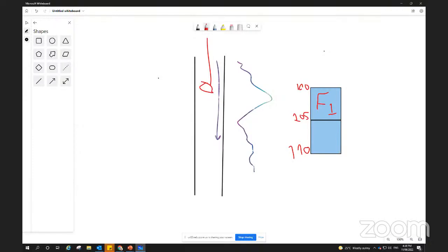The relation between depth and pressure should be in TVD or MD? It's up to you. If it's a vertical well, I don't think there will be much difference between TVD and MD. But if it's a horizontal well, it's preferred to use TVD.